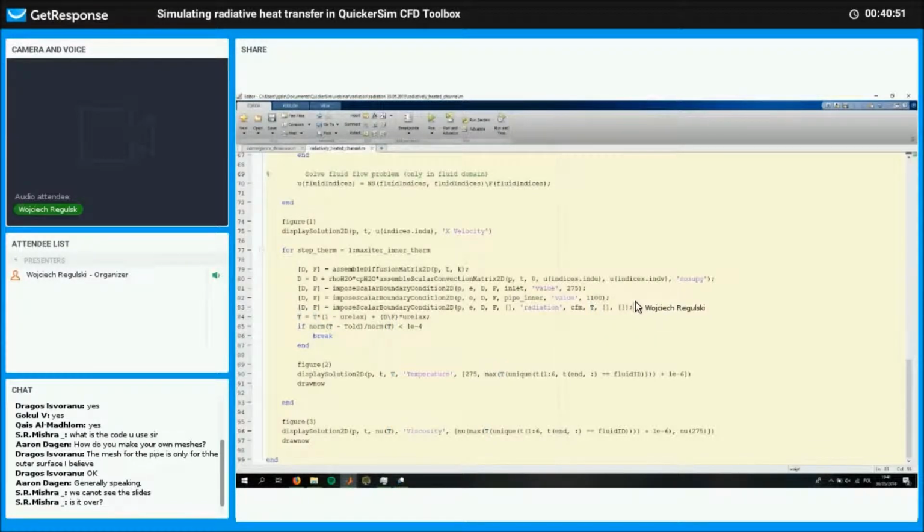What you can do here is define the emissivity and reflectivity of a surface. By default, the emissivity is 1, so it radiates as a black body would, and the reflectivity is 0, so a surface absorbs all radiation that reaches it. It's very simple to define, but for this case, I wanted to keep things fairly simple.